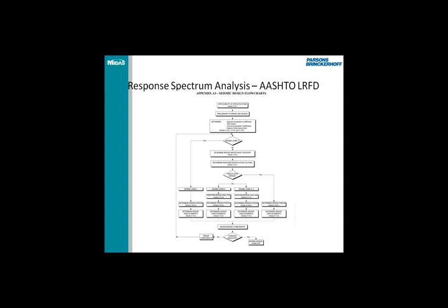Okay, so response spectrum analysis in the AASHTO LRFD. What I've got here are the flow charts that AASHTO provides you to tell you exactly what you need to do in order to determine your seismic forces and build your response spectrum.